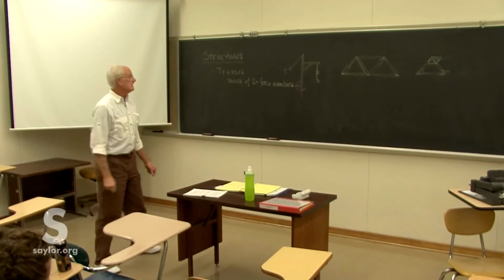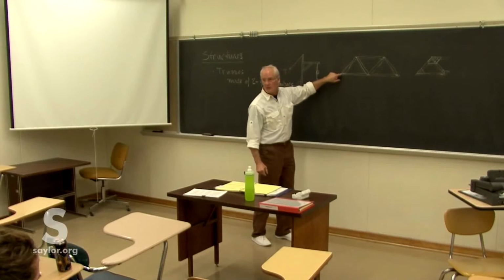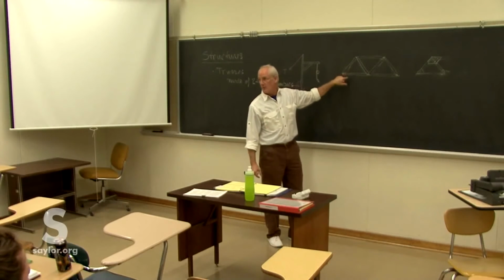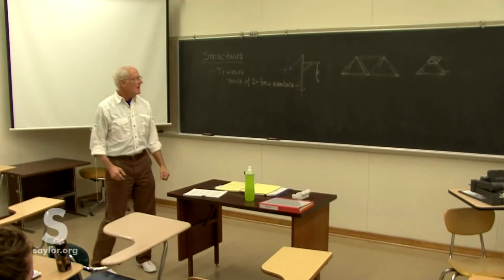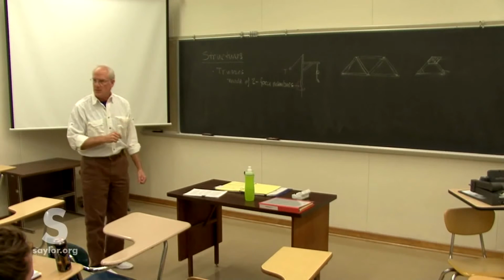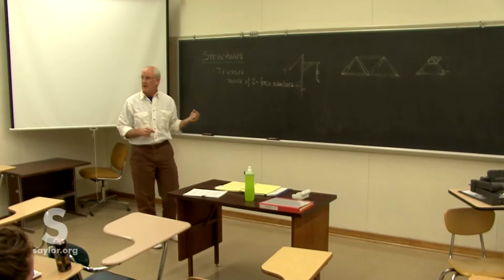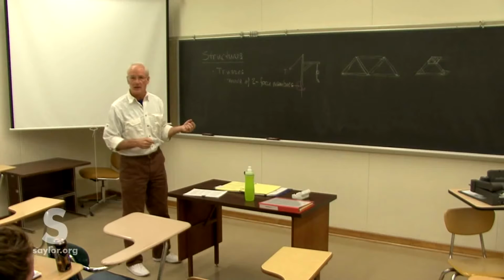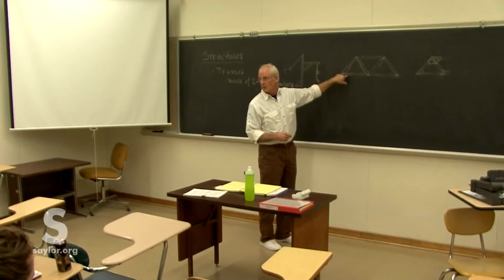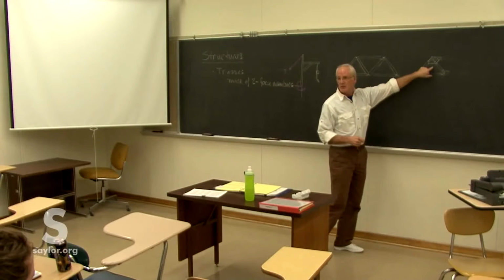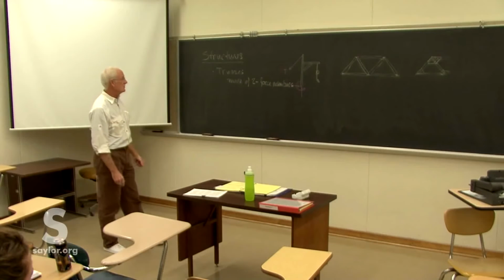What that does for us is it means the solutions we're going to find for these, and what we're going to look for is the forces at each of the joints on the pins, and thus the forces as well in the members themselves. What that does for us, the fact that we keep these as pinned joints, means that we're coming up with a very, very conservative design. We're going to come up with a design that really can't support a whole lot of force, such that when it's built in real life, it's going to be way overbuilt and have a huge factor of safety in it.